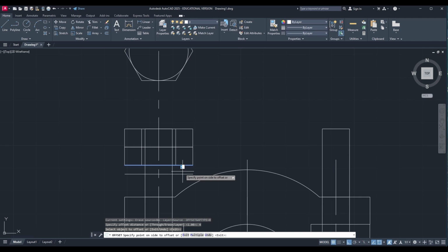Now one of the nuts becomes 12 mm. Delete that and extend the lines to make the thickness 12 mm. I will use the extend option and select whichever lines I want to extend. Okay, so these lines I need to extend. I'm making sure that it's 12 mm.